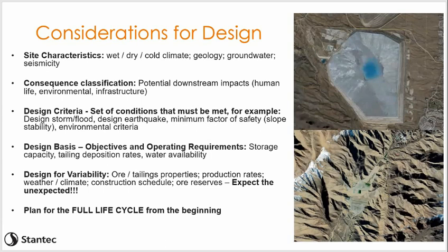Is it a dry climate like I discussed with our sites in Peru, where we're going to have a deficit of water and we're going to need to draw from local water sources and really minimize our losses? Is it a cold climate where we have to worry about freeze-thaw effects? These are all things that you're going to have to take into account in these dam designs. Understanding the local geology, local groundwater, and local seismicity are all huge components of these designs.